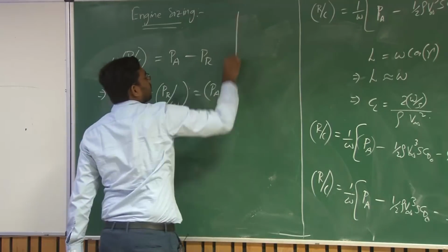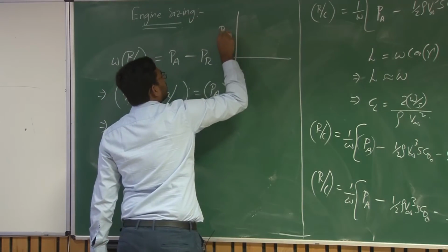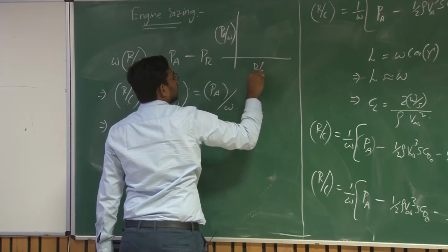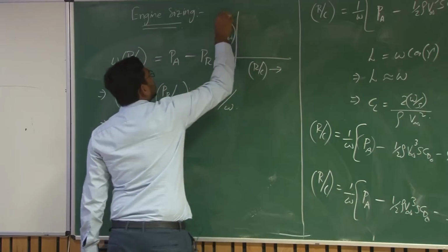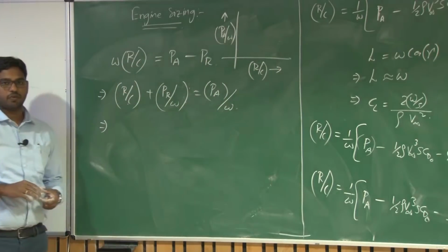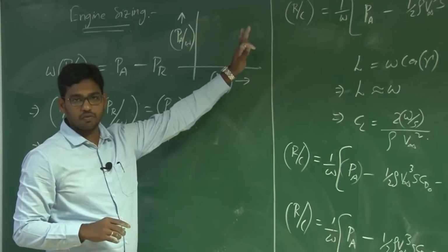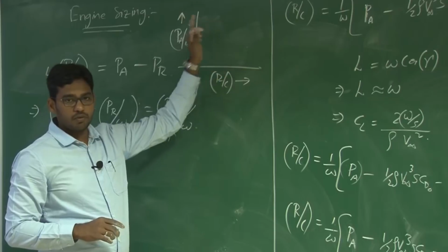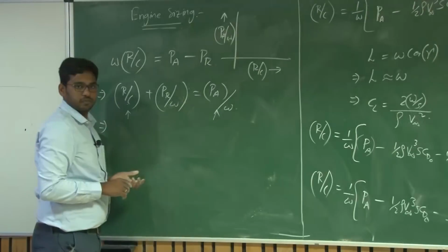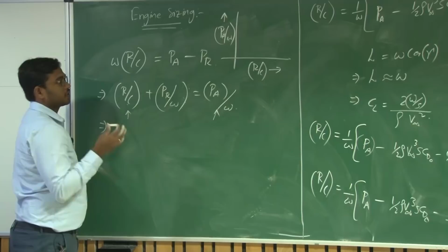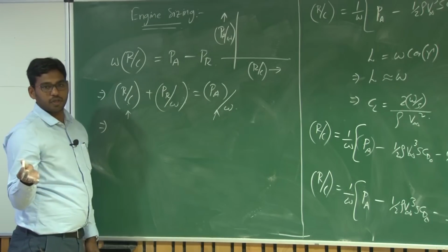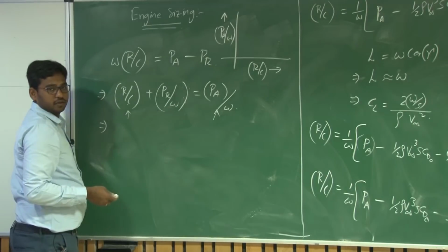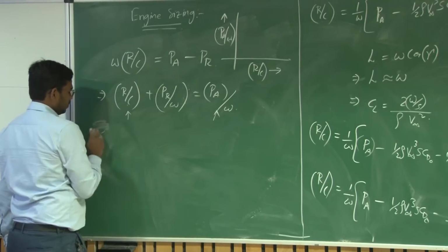If I want to get a plot of power available to weight ratio for different rates of climb, what should be the corresponding power available to weight ratio? What is the maximum rate of climb that your UAV has to perform? The corresponding power requirement you will select, and based upon that power requirement, you can select the corresponding engine, right? So how to calculate that? How to get that? So consider the steps.